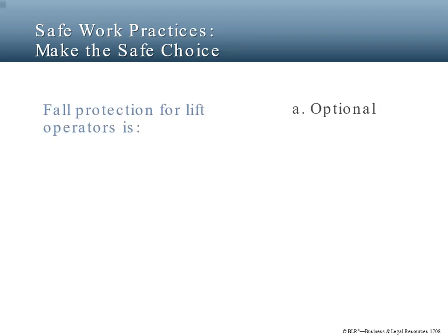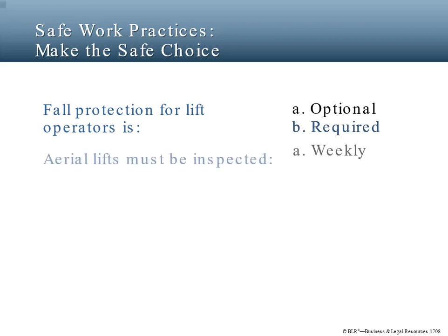Here's a quick multiple-choice quiz to test your knowledge of the safe work practices we've just reviewed. Fall protection for lift operators is A. Optional, or B. Required. Fall protection for lift operators is B. Required. Aerial lifts must be inspected A. Weekly, or B. Before each shift. The correct answer is B. Before each shift.